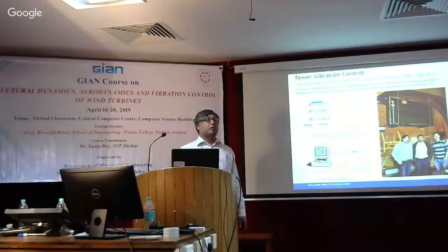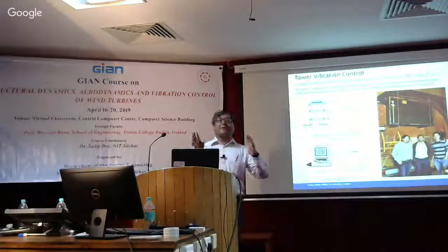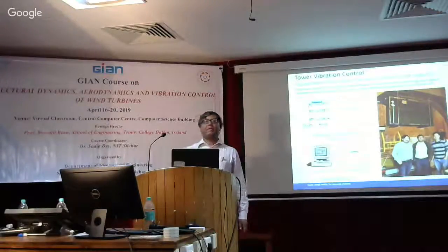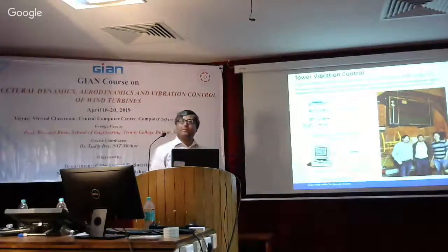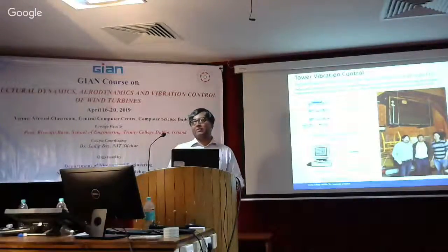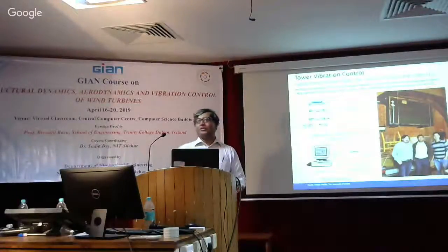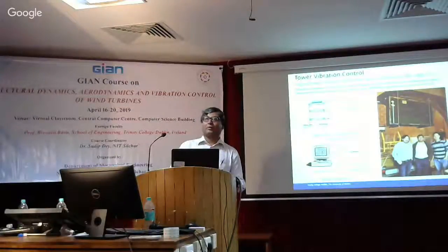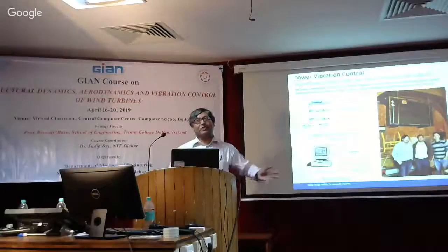And the main thing is that the control time delay is not there at all. So what you expect in the field is exactly happening now, because this is physically tested in full scale. All the delays are actually taken into account. Everything is happening in real time. But you definitely will have a delay, because when you use a computer, you do discretization and so on. That's why we use a delay compensation. So it's not a normal computer code that you run. You have to specially design the computer code to take this into account. We don't use continuous systems. We use discrete systems, something equivalent to what's called DSP. So all our dynamic systems are discrete systems, and we're not solving actual differential equations.